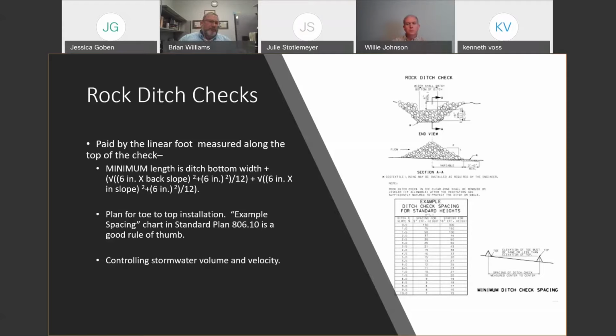The intent of the permit is that we are able to capture a 2-year 24-hour storm event with our BMPs. So if we put minimal BMPs out there in the design concept, and then construction has the philosophy that they think that we've designed it to meet the requirements, and they want to take a few more out of there, we're putting ourselves out there for liability.